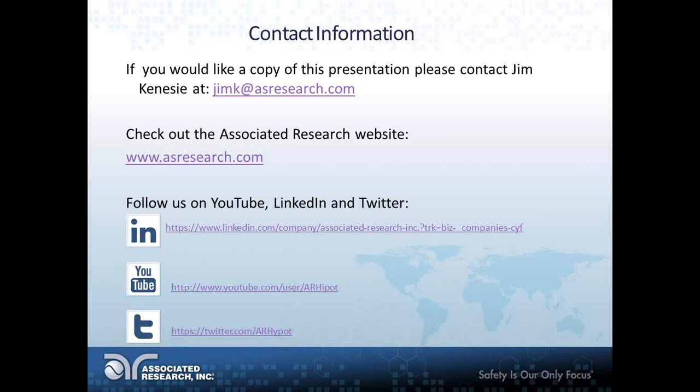Yes, Syed, there is one question here. Actually, I got a couple of questions. First one is, is there any way to lock out operators from making changes? I'm assuming that has to do more with the software than the scanner. Correct. That was a good question. Yes, the security feature on the Autoware software allows you to give permissions to different users. You can add a user and give that user just enough access to be able to execute the test that you have already set up. So the user cannot go in and change any settings on your test. That includes scanner settings, test parameters, and test types.